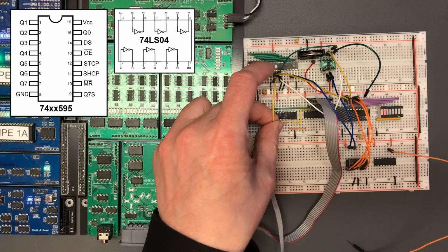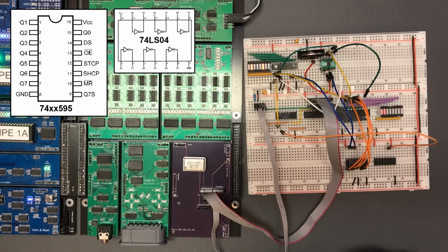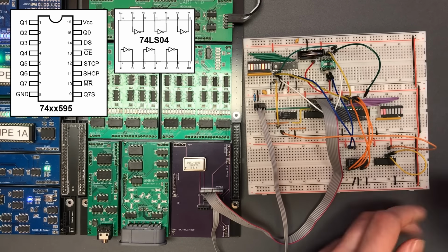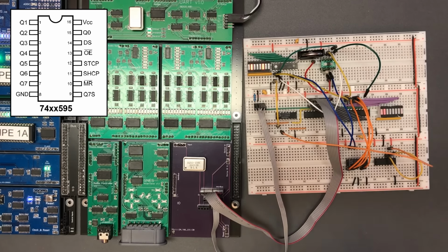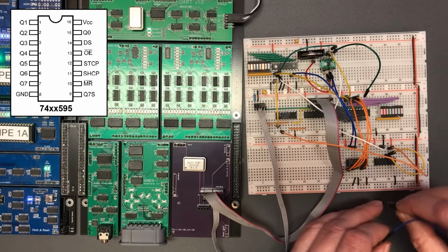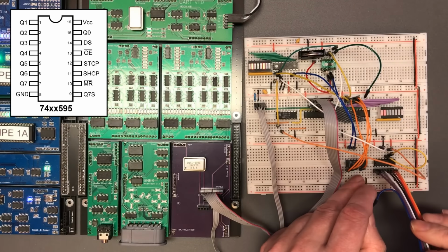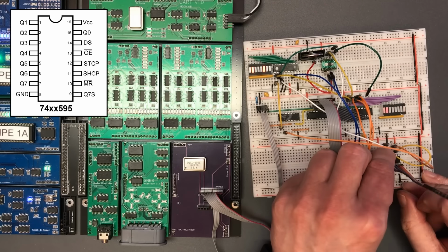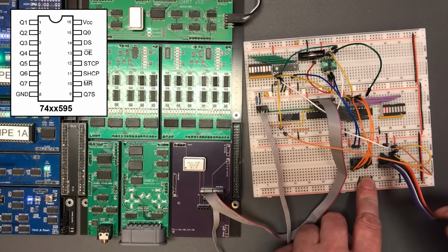All right, then we've got a latch line. I'm just going to fire that off the same clock signal for now. An output enable. Let's just pull that low. And then our data in line. The outputs are kind of opposite way around than would be convenient for us. And they're split between Q0 over here and 1 through 7 over here. So I've made up this cable that makes things a bit easier.